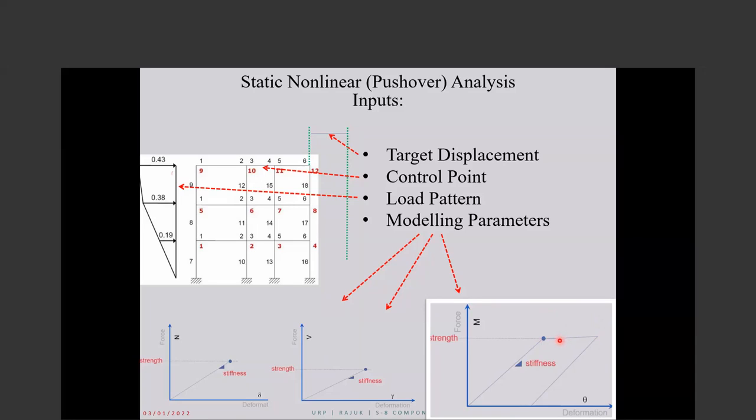In the third possible ending, the force control parameters won't get damaged. The building reaches the target displacement, but some of the deformation control parameters will pass their limit and get damaged, and we assign the performance level of the building based on their damages, as we will explain later.